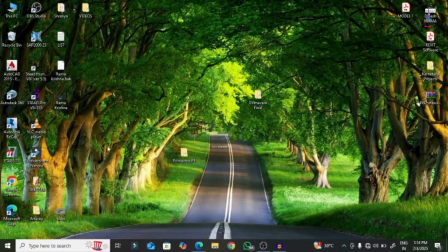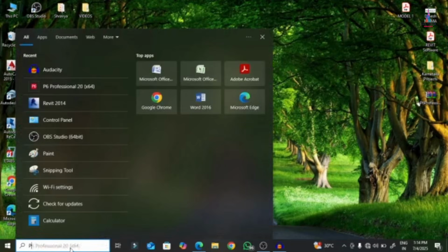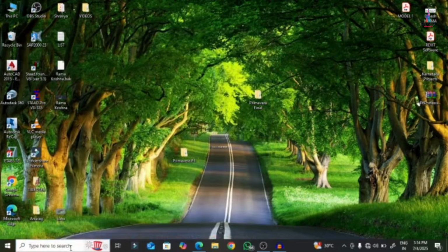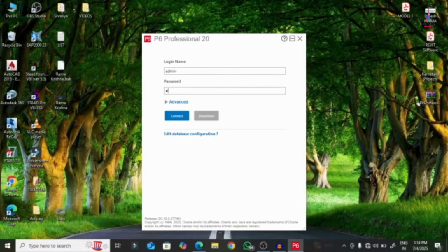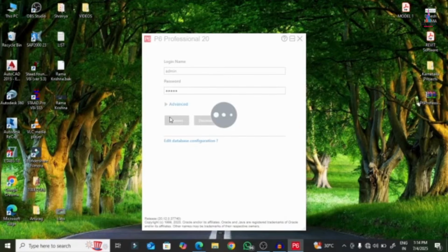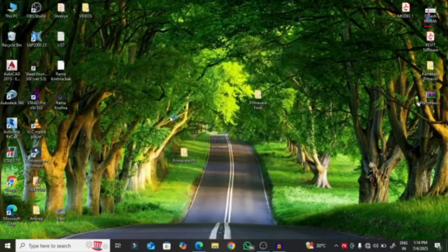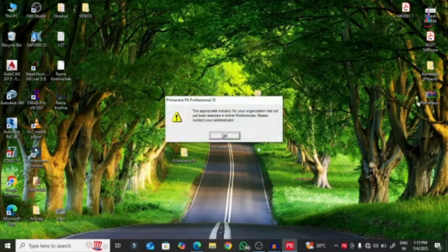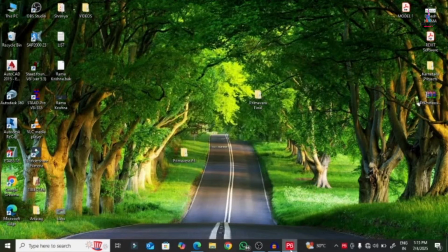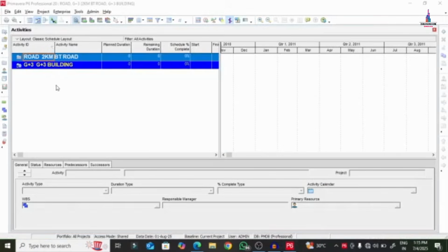So initially I will open my Primavera P6 software. Enter your password. Just I am selecting my password. Here click on the connect option. So these are the EPS we already created in the previous classes. So for this EPS I will create the WBS.